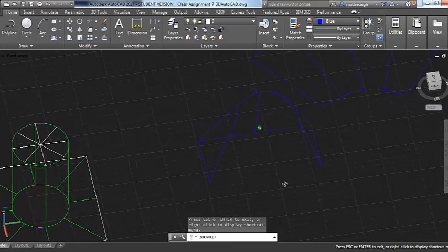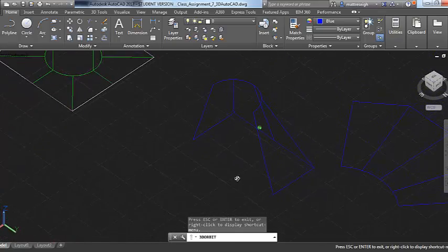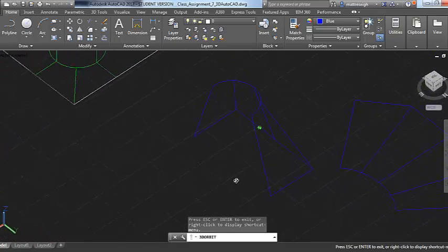Yeah, so this one I'm actually press braking. Let me spin around, just give it a view here. I'm press braking from the center lines of these patterns. This edge is going to stay straight. All the press brake work is going to go to the corner that's turned 90 degrees and up halfway.